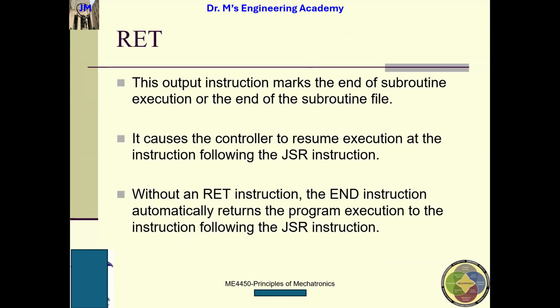RET, return. It marks the end of subroutine execution or the end of the subroutine file, and causes the controller to resume execution at the instruction following the JSR. Without the RET instruction, the END instruction automatically returns the program execution to the instruction following the JSR. And for very beginners, guys, I would suggest you use RET all the time.